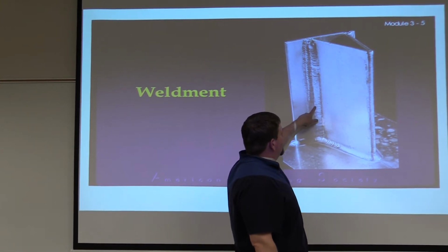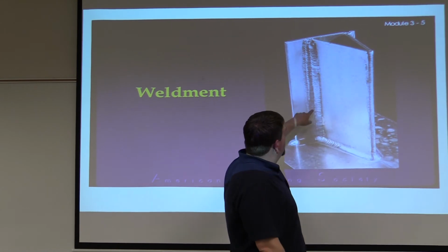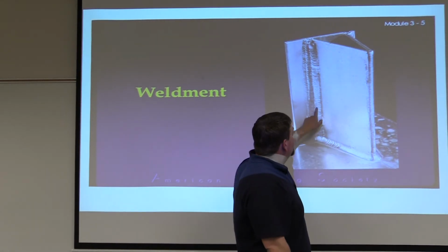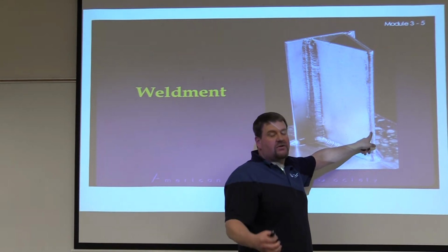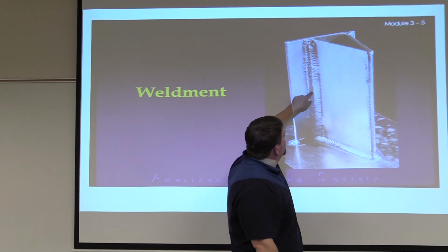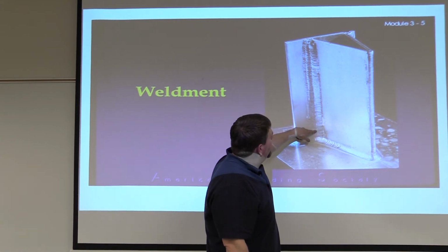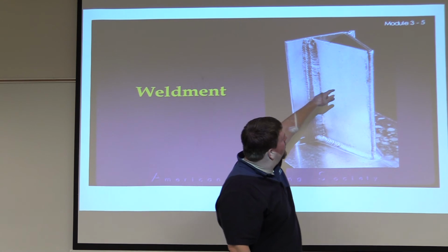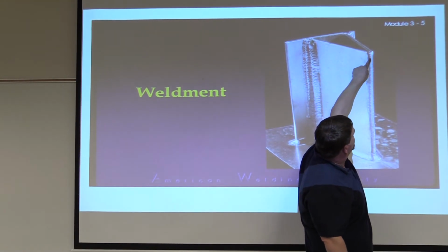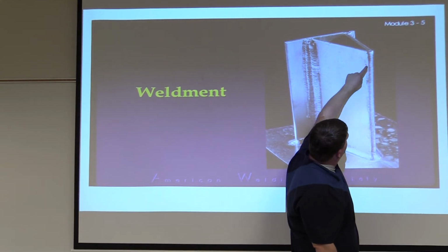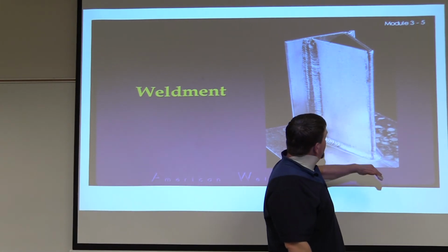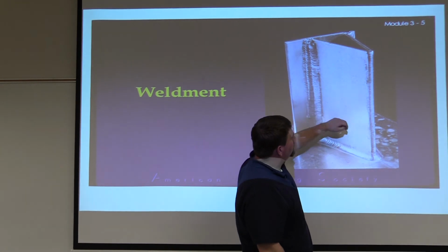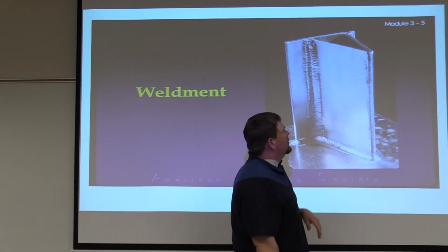So in this case, this is a different weld. This is one piece, but this is a different weld than this is, especially in this position, okay? This can even be a different weld than this. Naturally, it's a different joint. But what if from this standpoint here, it's in an uphill progression. I can see it ends at the top there, okay? But in this one right here, they started at the top. I can evaluate from the weld. I can see the ripples are going a different way versus this one, the ripples are going in this direction. So this was done with an uphill progression. This was done with a downhill progression, okay?